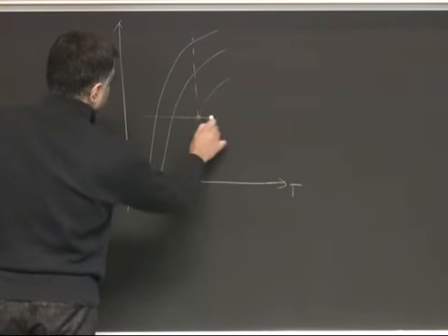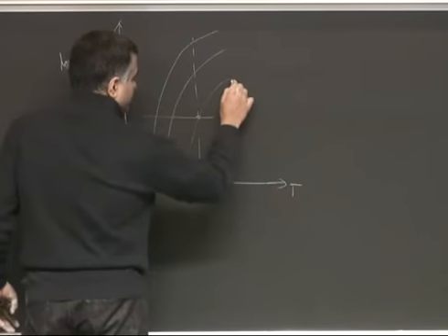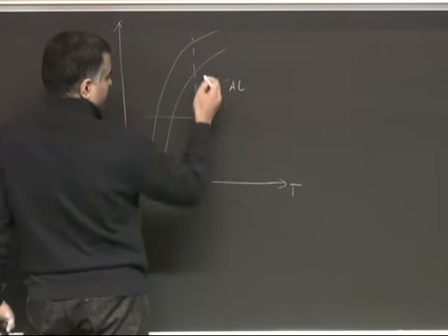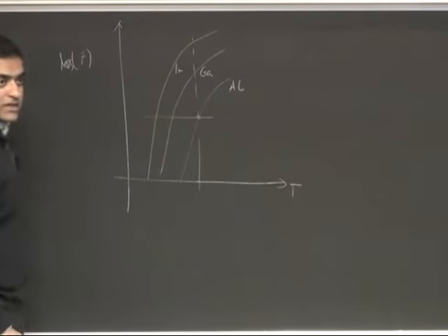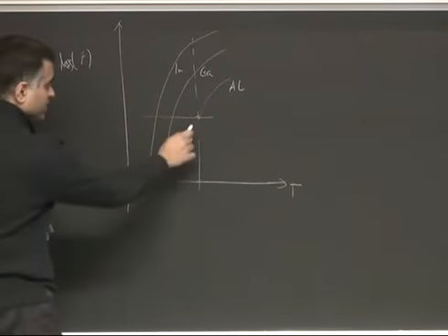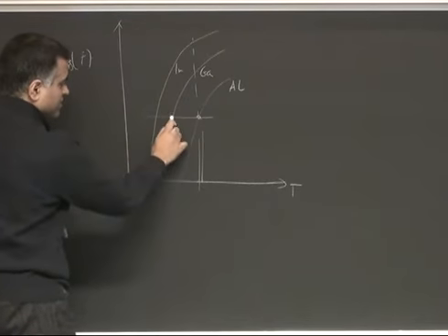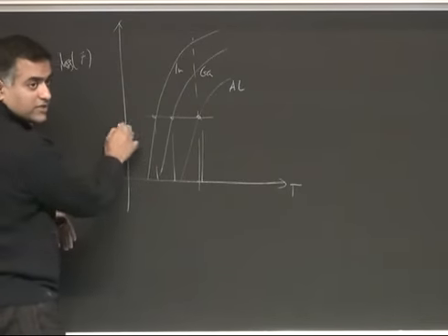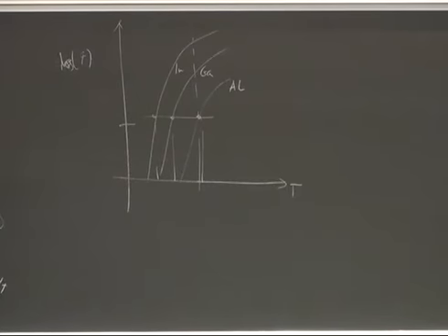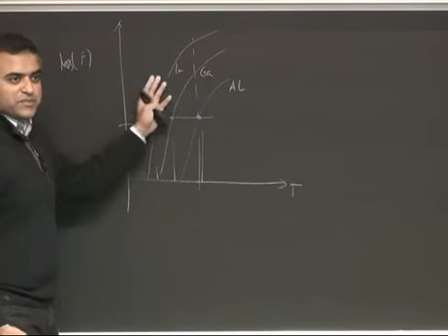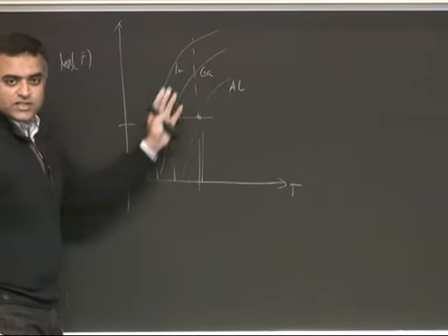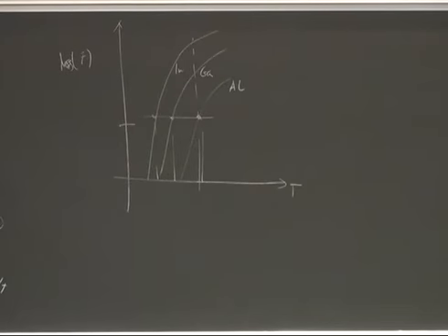As an example, in compound semiconductors, the three very important elements are aluminum, gallium, and indium, right? So if you want the same flux, typically you would need a higher temperature with aluminum than for gallium. And typically this is how it's going to be, right? It's not a very good way of looking at it, but the heavier the element, generally you would need a little more temperature to get the same flux. So generally, it's not all the time.